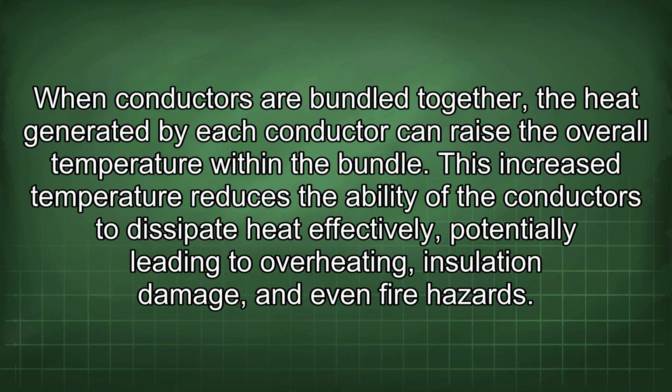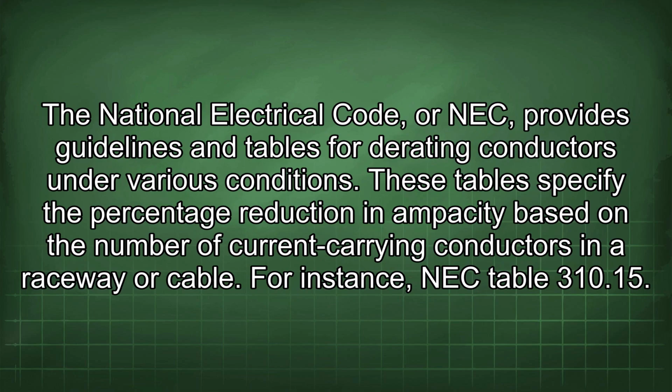When conductors are bundled together, the heat generated by each conductor can raise the overall temperature within the bundle. This increased temperature reduces the ability of the conductors to dissipate heat effectively, potentially leading to overheating, insulation damage, and even fire hazards. The National Electrical Code, or NEC, provides guidelines and tables for derating conductors under various conditions.